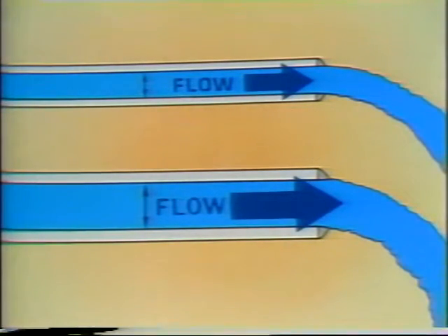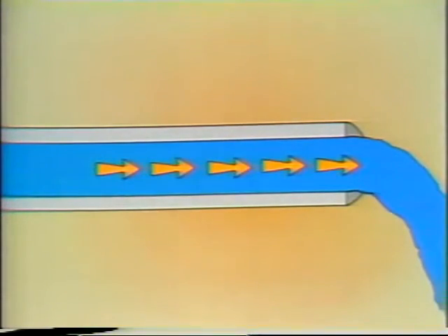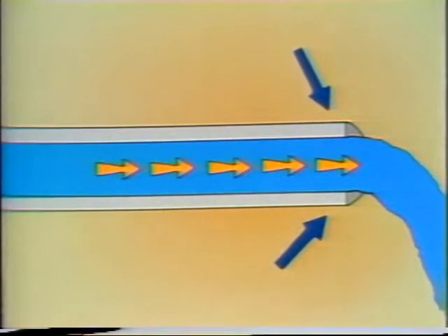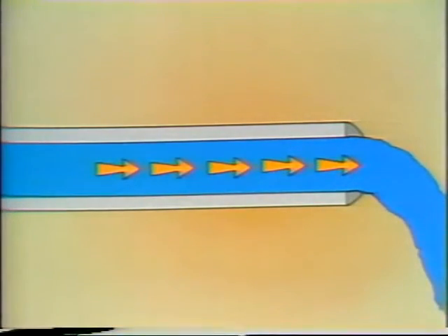However, flow through a pipe is very complicated because of the many things which affect flow. We'll simplify our discussion by only considering those aspects of the flow that you'll be able to see in your job. In a long run of pipe such as this, the velocity of the fluid, which in this case is water, remains the same throughout the pipe. The reason for this is simply that since the fluid is incompressible, what's going in one end at a given rate has to be coming out the other at the same rate. While velocity remains the same over the entire length of pipe, pressure, symbolized by the letter P, drops. This is always true because flow couldn't occur without differential pressure.